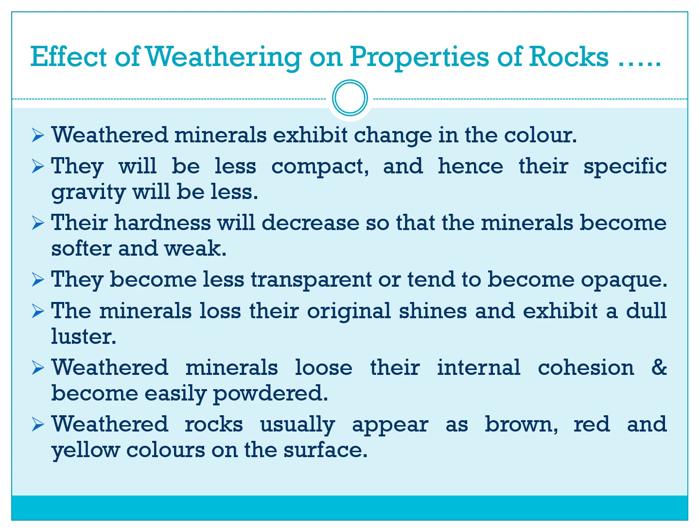Effect of weathering on properties of rocks. Weathering transforms rocks from their original relatively strong and cohesive state into weaker, more easily eroded materials. These changes have significant implications for soil formation, landscape evolution, and the overall stability of the Earth's surface. Weathered minerals exhibit change in color. They will be less compact and hence their specific gravity will be less. Their hardness will decrease so that the minerals become softer and weak.